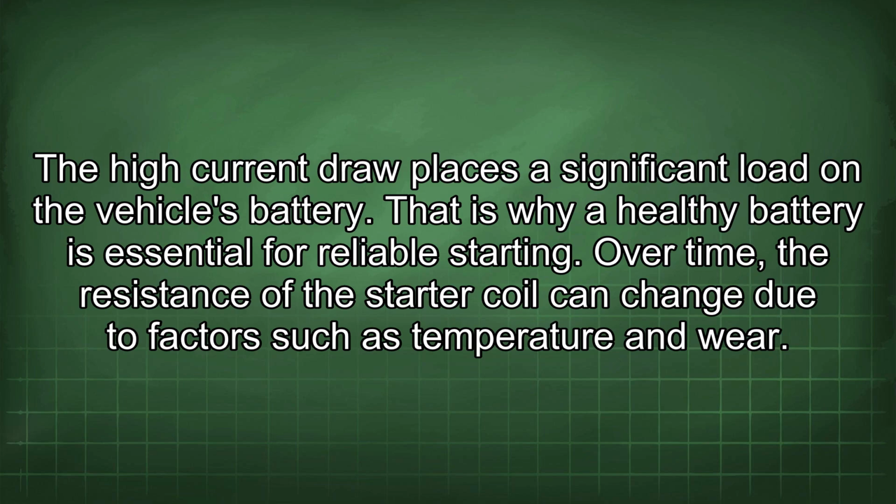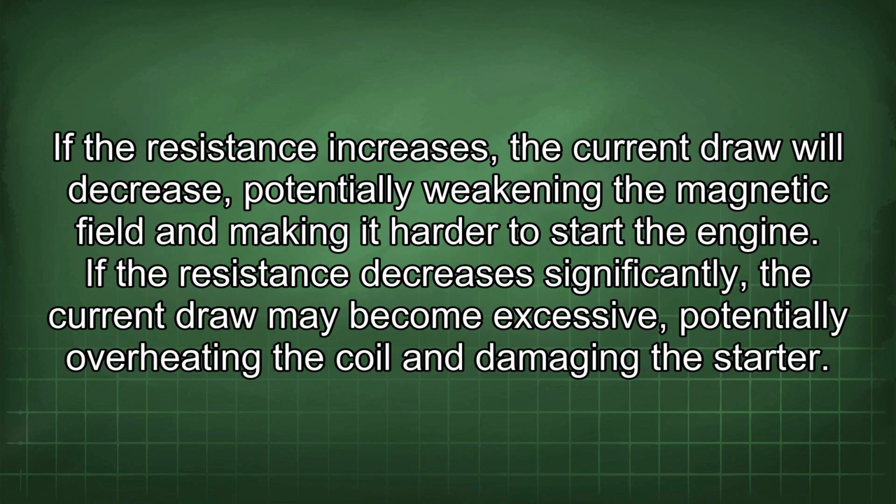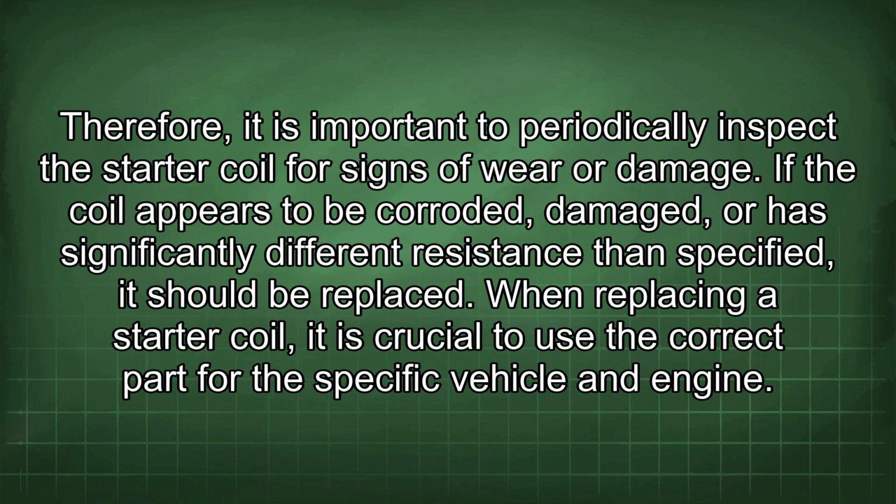Over time, the resistance of the starter coil can change due to factors such as temperature and wear. High temperatures can increase the resistance of the coil, while corrosion or damage to the coil windings can also alter its resistance. Changes in resistance can affect the current draw and the performance of the starter. If the resistance increases, the current draw will decrease, potentially weakening the magnetic field and making it harder to start the engine. If the resistance decreases significantly, the current draw may become excessive, potentially overheating the coil and damaging the starter. Therefore, it is important to periodically inspect the starter coil for signs of wear or damage.